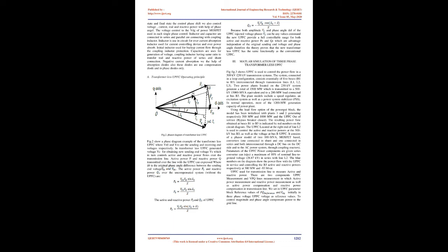Because both the amplitude and the phase angle delta of the UPFC injected voltage phasor can be any values, the command of the new UPFC provides a fully controllable range for both active and reactive power, Pc and Qc, which are independent of the original sending end voltage and phase angle. Therefore the theory proves that the new transformer-less UPFC has the same functionality as the conventional UPFC.